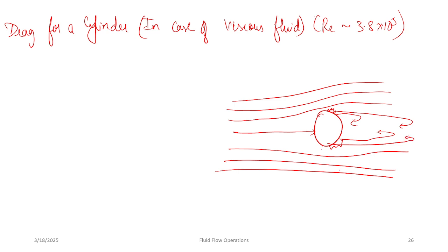So for the rear half of the cylinder, just like the case of a divergent pipe, the flow gradually decelerates with the velocity gradient reaching zero. This point is called the separation point, where downstream flow gets reversals and also develops eddies. The fluid particles in and around the boundary layer mix with each other by the mixing action of the turbulent flow. As the turbulent nature of the fluid increases because of high Reynolds number, there will be rapid mixing because of this turbulent action.